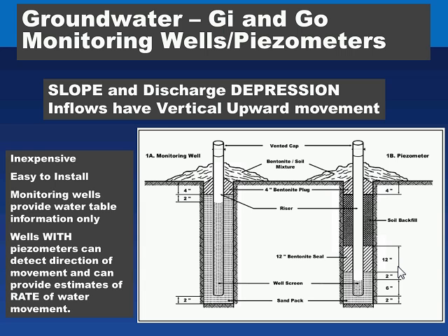This is direct evidence of groundwater discharge. In certain cases, we can come up with estimates of the actual rate of water movement using some soil hydrodynamic and saturated hydraulic conductivity calculations, but the qualitative knowledge of whether or not the water is discharging is valuable.